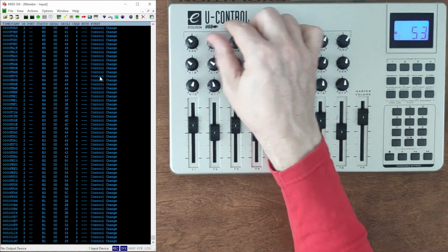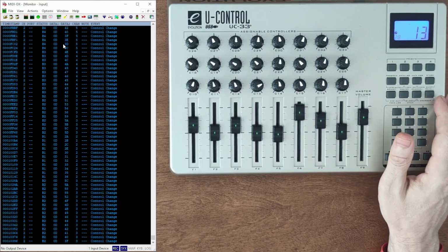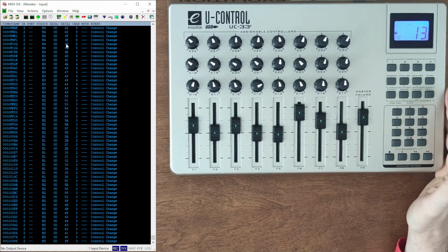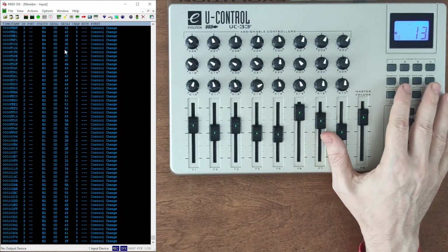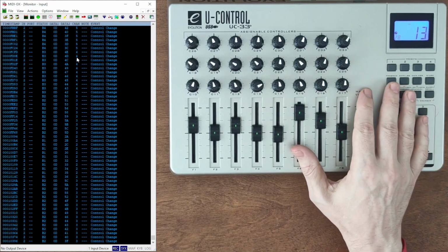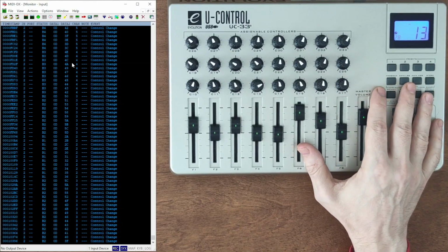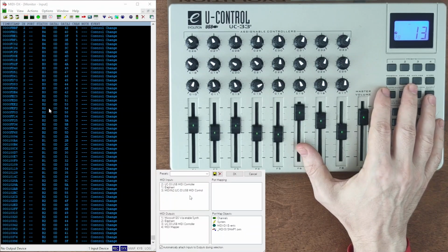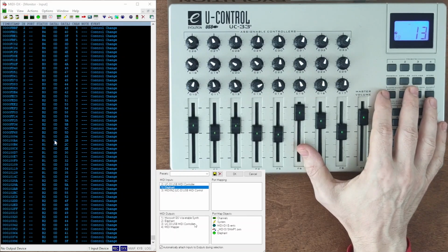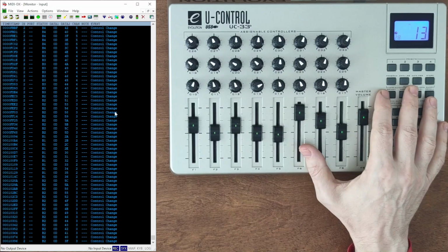And in this third part, we will program our unit with Enigma software. To run Enigma software, we need to unbind the device with the option MIDI Devices menu and select a device other than UC-33 in our MidiOX, which will stay running.